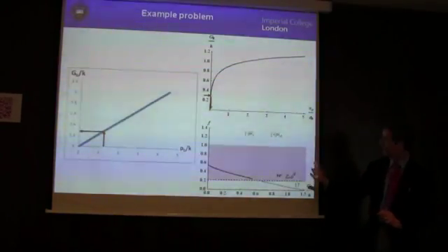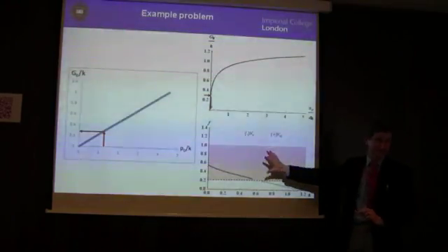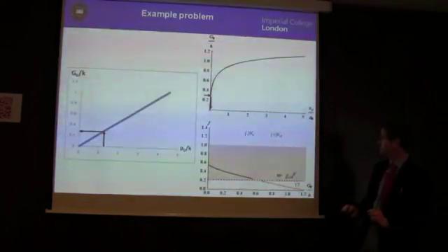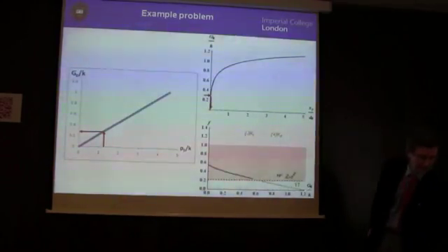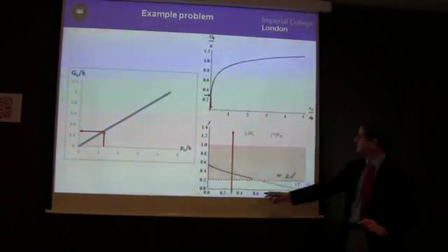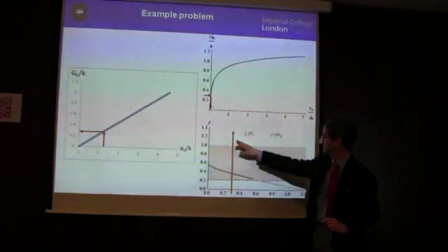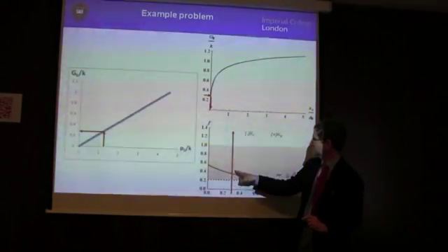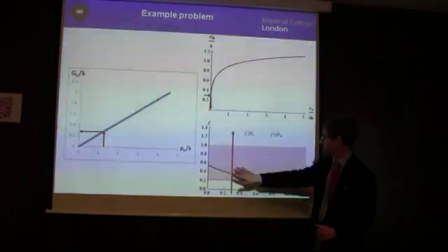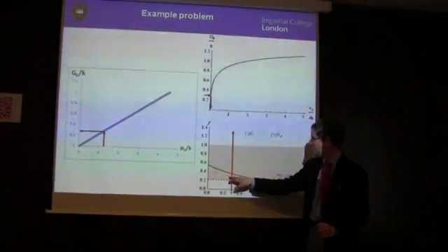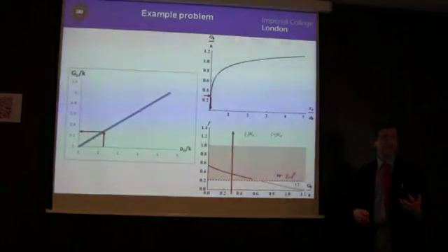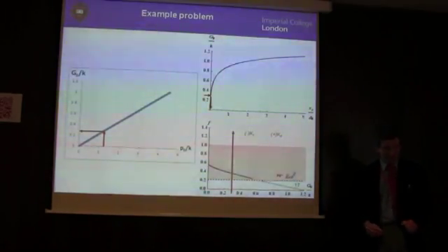If you then apply it to this diagram that I just showed you here, where we said you get sticking here, slip here, then you can see that for this value of G0 over K, if the friction's bigger than at least this value, about 0.4, we're up here where you get stick, whereas if it's the very low value down here, then you'll get slip, and fretting will be important.